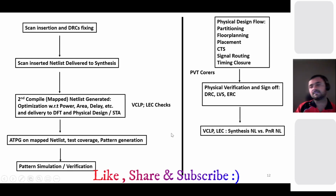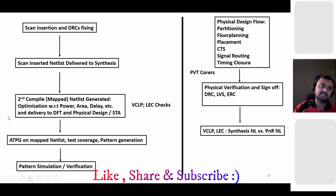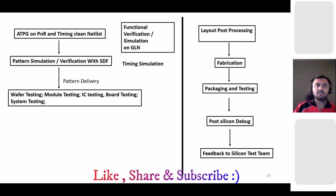All the things means ATPG. So then you get the PNR netlist, which is a timing clean or timing closed netlist, and then you perform the final ATPG on that. The previous ATPG is just to see that your flow works correctly and there is no issue, but that is not the one which you are going to deliver to the ATE or test team to test on the silicon. So once you receive the PNR timing closed netlist, you do the ATPG,